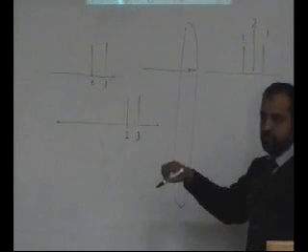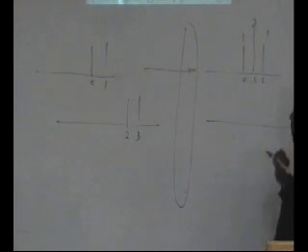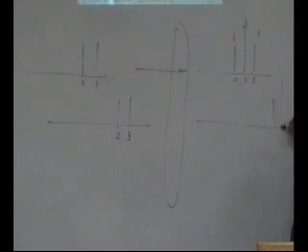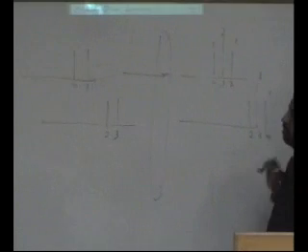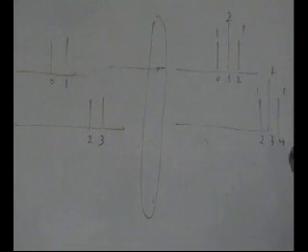Adding in the previous value. Here, this is index 0, 1, 2. If you shift the signal to 2, 3, you'll get the same answer only shifted to 2, 3 and 4. If a system obeys this, it is a time invariant or shift invariant system.